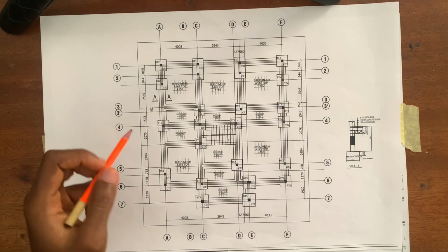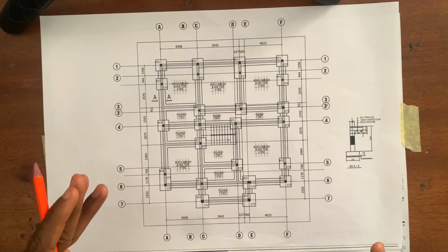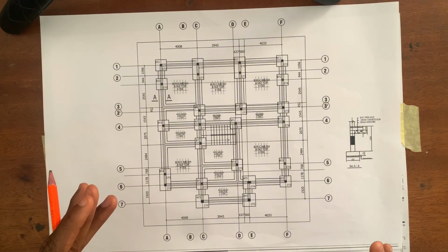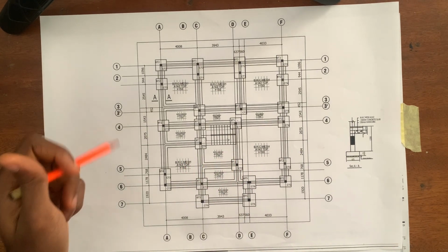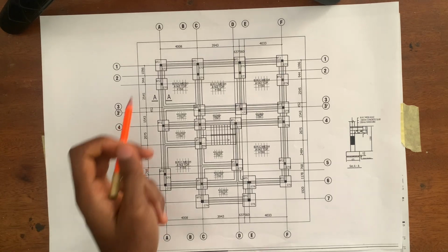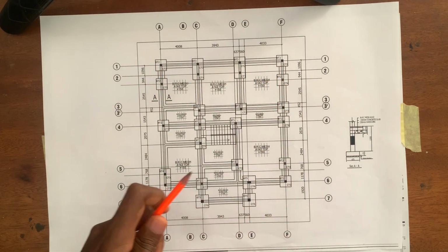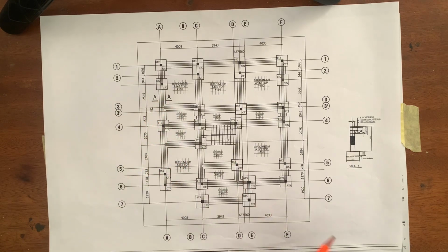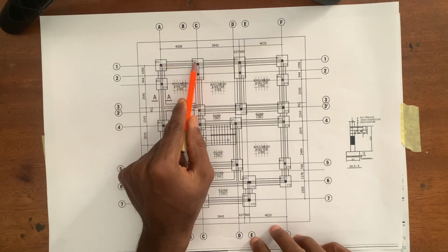So in order to get the distance for this trench, what you need to look at is the dimension given to you in the drawing. Now, what kind of dimension are you seeing in this drawing? Yes, center to center dimension. So center to center dimension is what was used to dimension this drawing. With this center to center dimension, we can determine the distance for each of the trench.